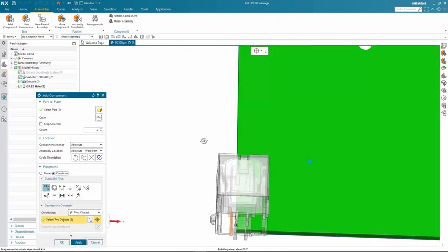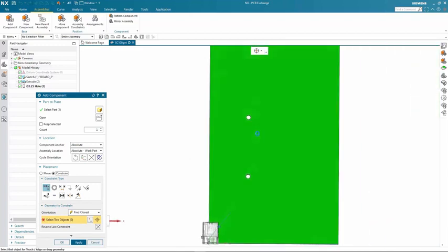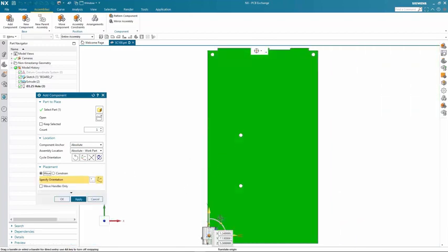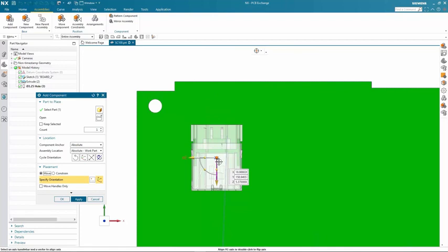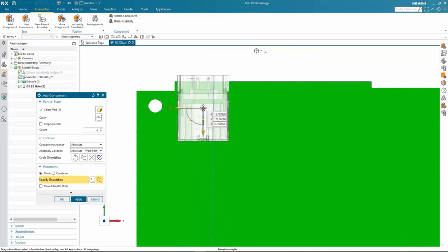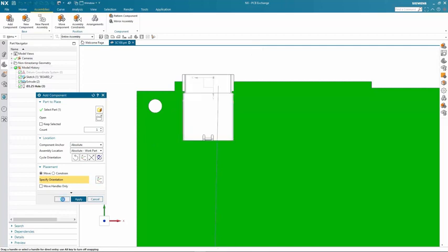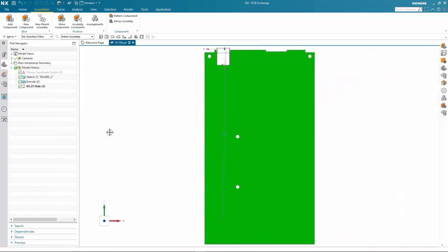I will first define a touch align constraint to mate the bottommost surface of the USB connector to the topmost surface of the board geometry. Then, I'll use dynamic movement to rotate and offset the component to be placed in the desired location as to not interfere with my mechanical models or my design rules in our domain.